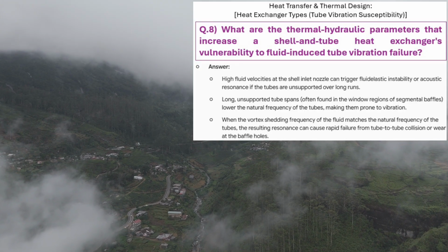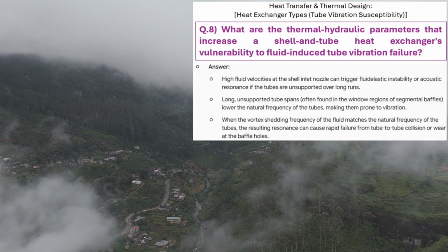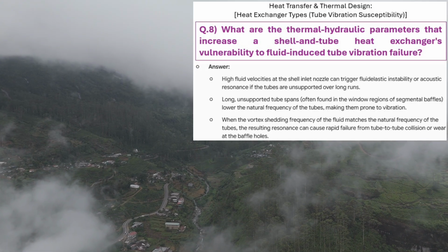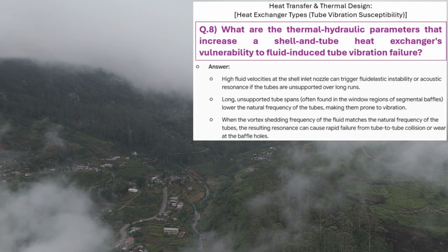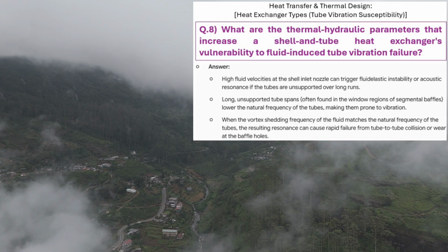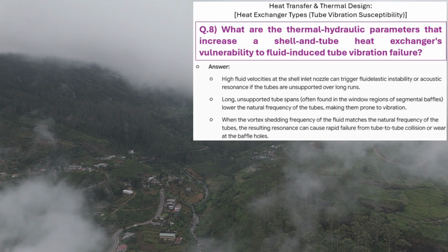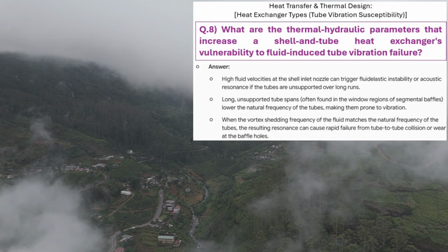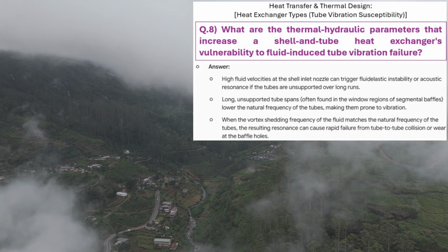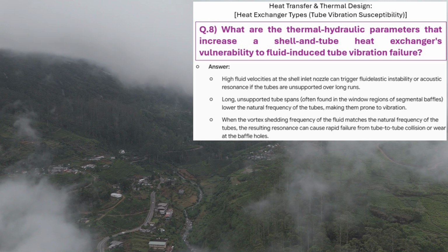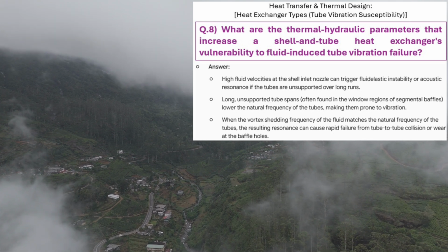Exactly. Now, acoustic resonance is a different beast, primarily occurring in gas flows. The high-velocity gas shedding creates a transverse acoustic standing wave that bounces between the steel walls of the shell. And if the vortex shedding excites this standing wave, the fluctuating pressure violently hammers the tubes, causing an ear-shattering noise and rapid fatigue. The fluid elastic instability is even worse, isn't it?